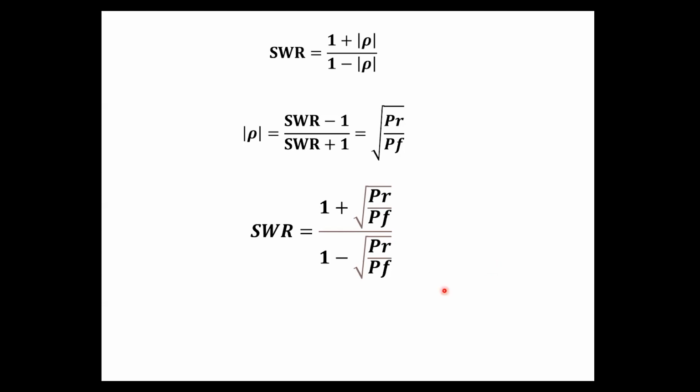One other thing that we can do, since we've got these antenna analyzers, I can go to my radio and I can measure what the actual impedance is at the radio.